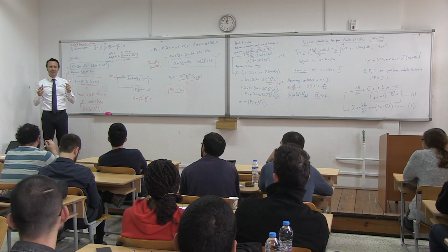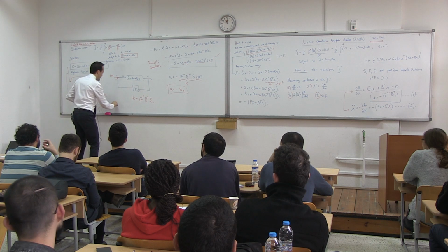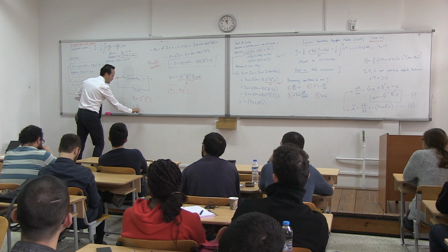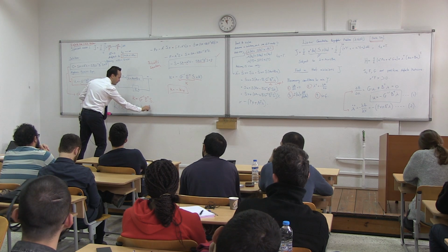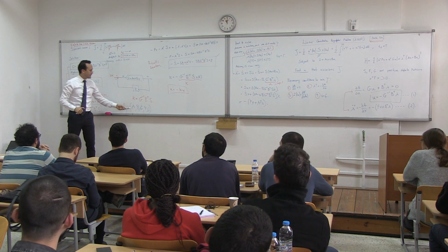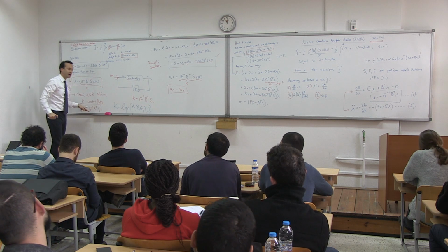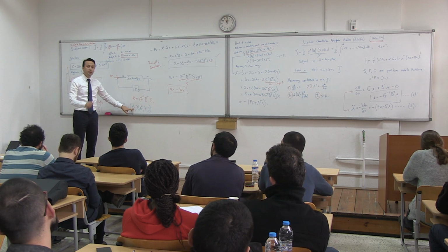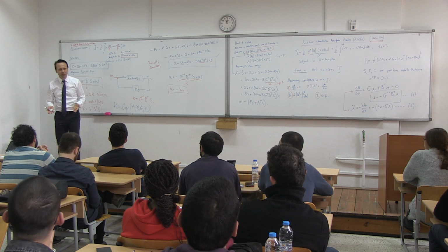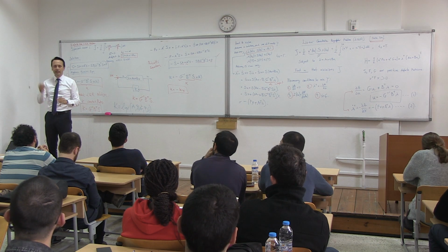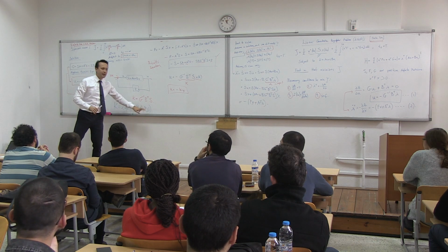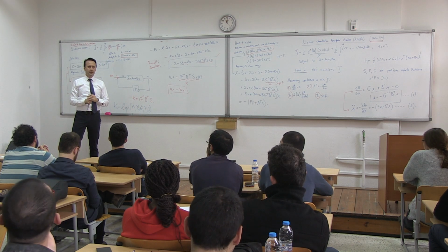In MATLAB, it's one command. Okay? In MATLAB, you just write K = lqr(A, B, G, F). And there's a 0 here, but you'll see. So you'll get A, B, G, F, 0, and it will calculate K immediately. You just need to plug in A, B, and then choose G and F. It will calculate LQR. So that's not the problem. The problem is not solving this. MATLAB does it in less than a second. The problem is, how do you choose G and F? Does that make sense? Okay.